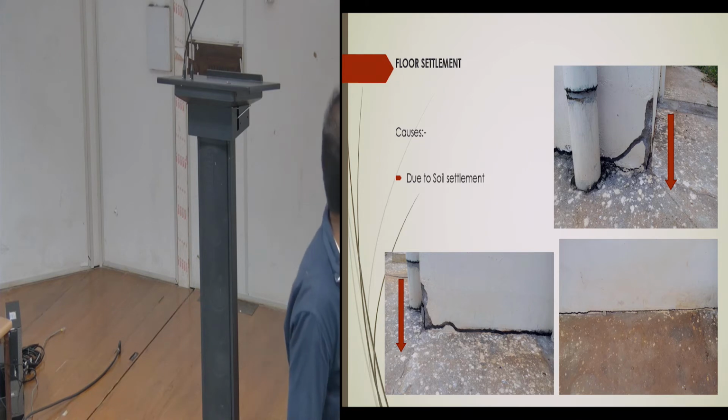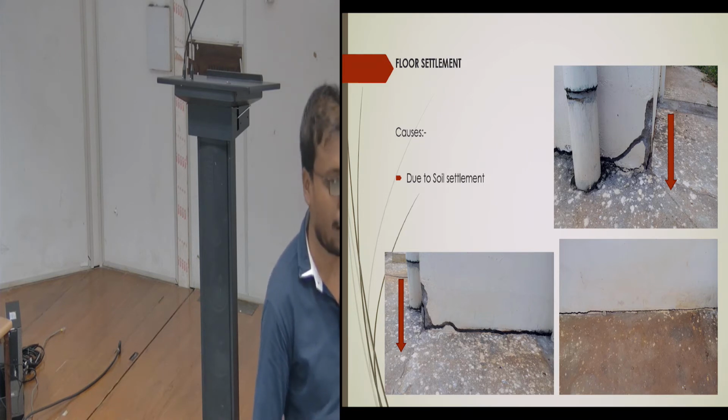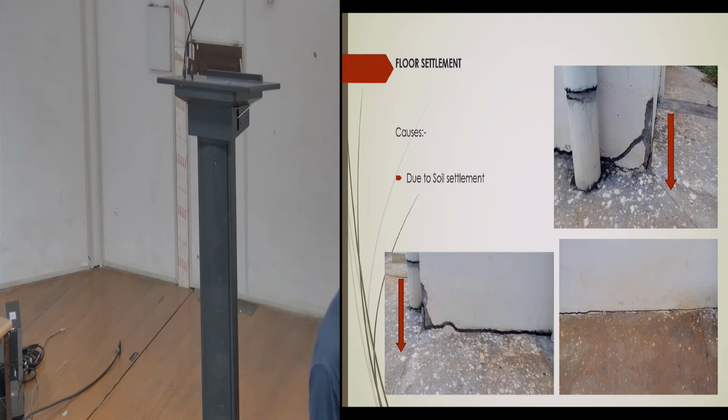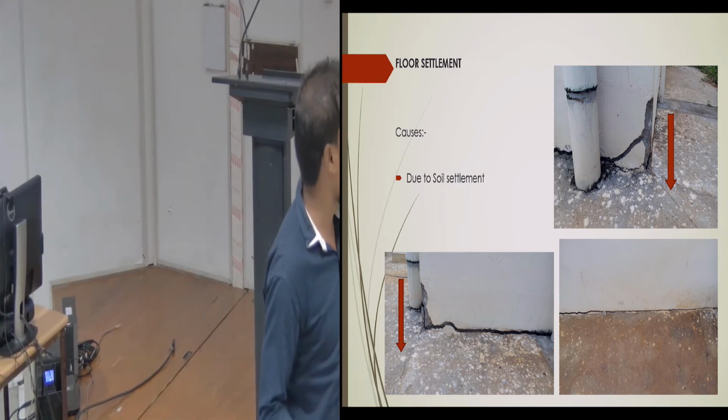So, it is because of settlement. Actually, what happens during construction of the footing? The soil beside the foundation is not compacted well. So, slowly, gradually, it consolidates after the construction. Because of the construction, it settles, and that causes the crack.